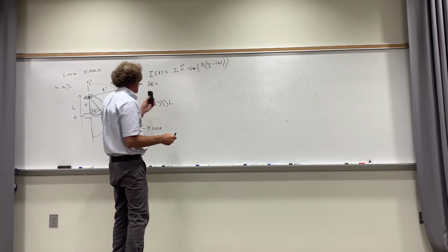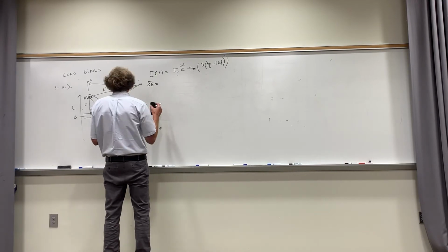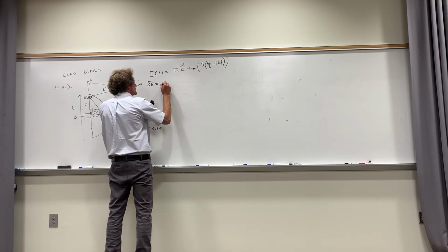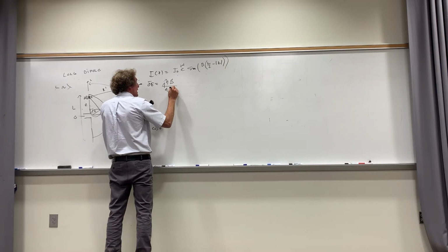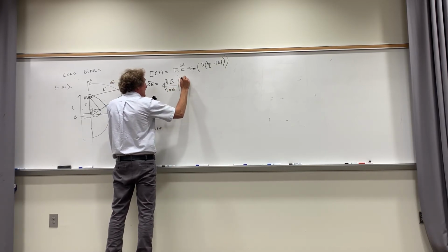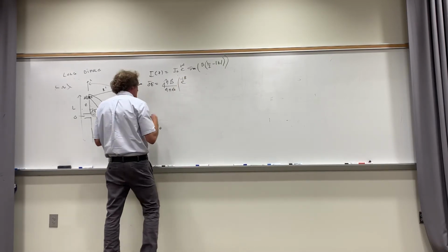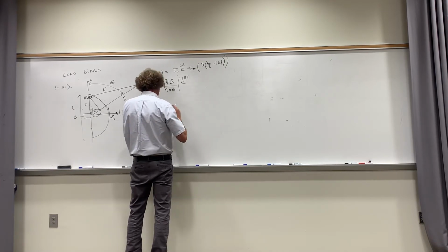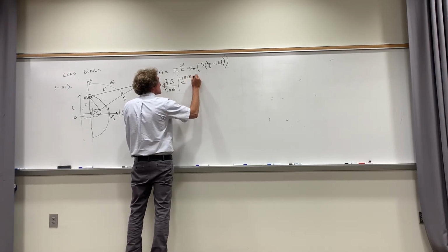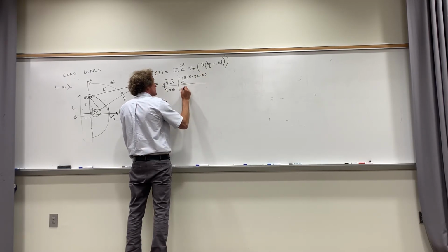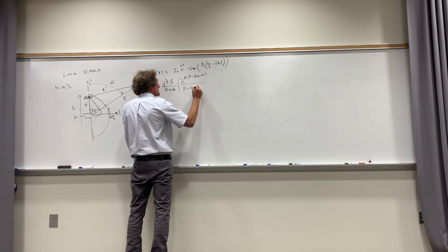So now I say what dE is. Now we take a look at this as causing the electric field from a short dipole. So we simply put j eta beta over 4 pi epsilon naught. Then we take it and put e to the minus j beta, and here it's r prime, which would be r minus z cosine theta, divided by r, and that's really r minus z cosine theta. I'm going to clean this up in a second.